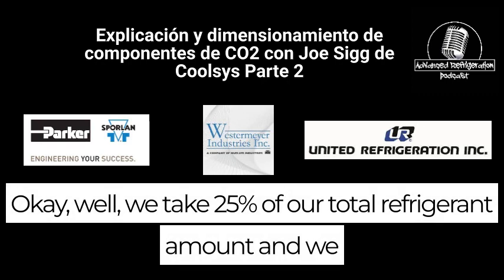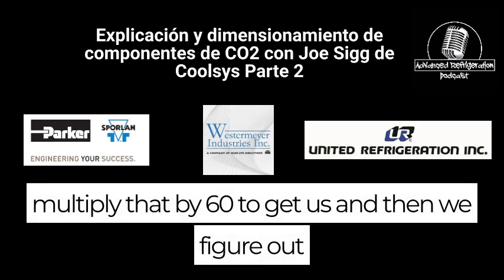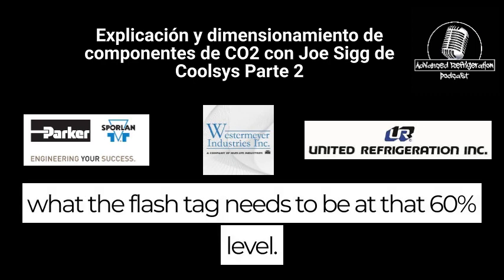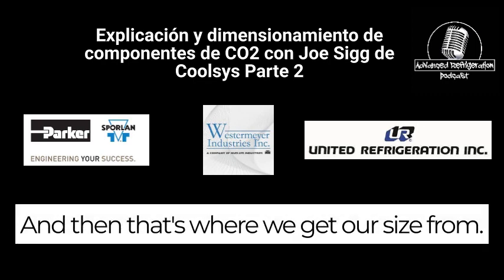Okay. Well, we take 25% of our total refrigerant amount, and we multiply that by 60, and then we figure out what the flash tank needs to be at that 60% level. And that's where we get our size from.